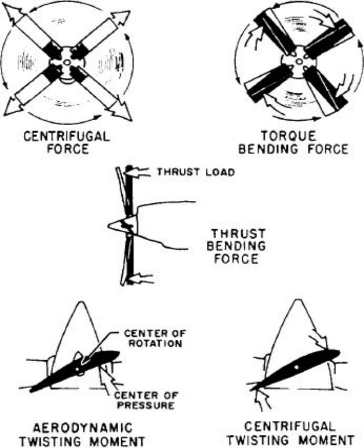What are the aerodynamic forces and loads acting on a rotating propeller blade? Centrifugal force, aerodynamic twisting, centrifugal twisting, torque bending, thrust bending.